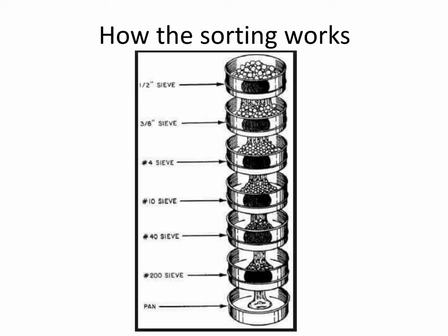They do exist, but there are other factors happening when you get to really tiny particles that keep them together, van der Waals forces, electrical forces, and so just shaking usually doesn't separate them. There are additional tests you'll learn about in soils to separate out samples below the 200. The 200 is tiny. We're talking about 0.075 millimeters as your opening size.